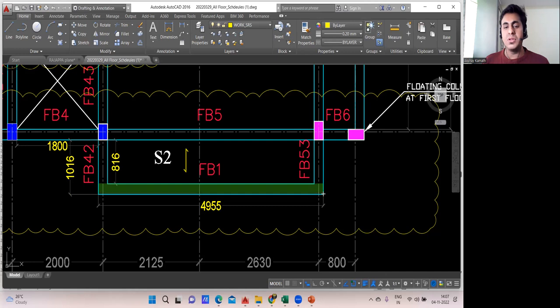So my beam shuttering will be completely okay. In this way I'll take. Now of course the beam bottom will come. Your beam bottom length is 4.995. You multiply by the width of this beam, your beam bottom is done. Next, here outside shuttering will come. Why am I calling it outside shuttering? Because there is no slab in this part. So whenever there is no slab adjacent to your beam, you have to call it outside shuttering. So this becomes my outside shuttering.